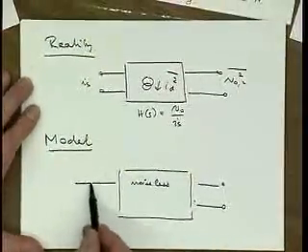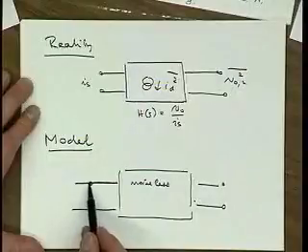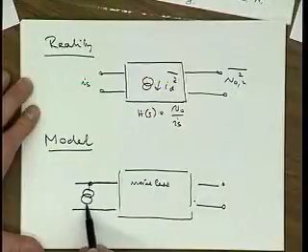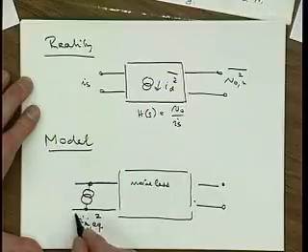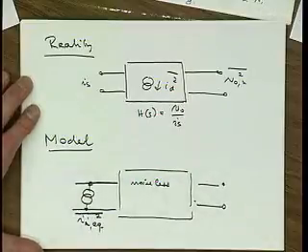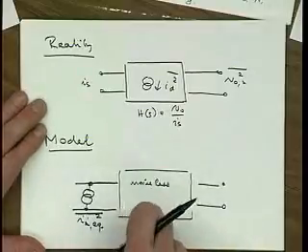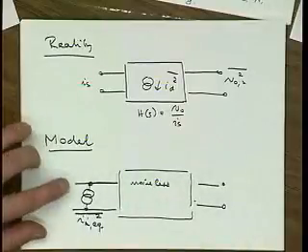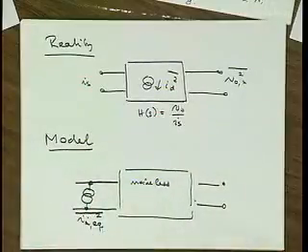And now, in order to make these equal, we introduce a fictitious noise source here at the input, I_EQ, the equivalent input referred noise source, that models all the noise that's actually added by the real circuit. So it's a little bit deceptive, right? This noise source plainly doesn't exist. It's just here for modeling.